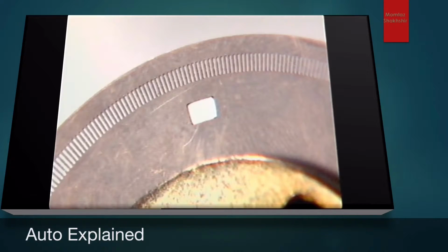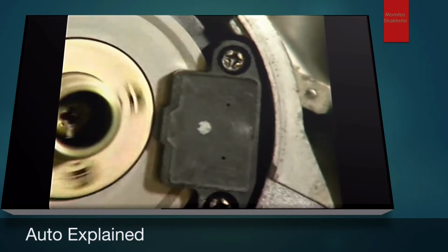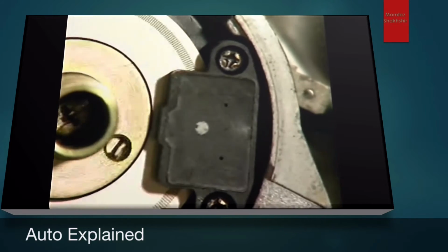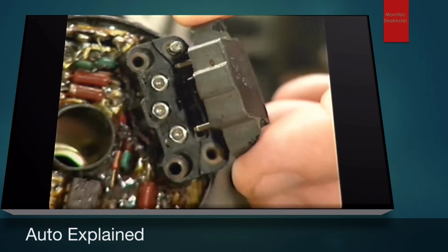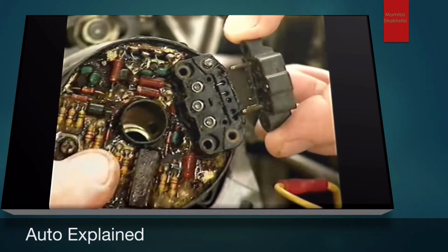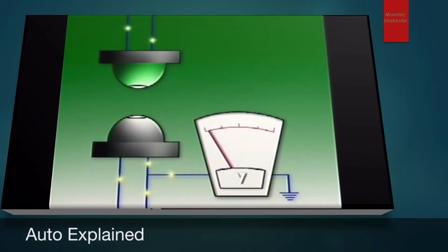As the rotor plate turns, it passes between 2 sets of diodes positioned in line with the slits. The diodes above the rotor plate are light-emitting diodes, while the ones below are photosensitive diodes. When provided with a suitable voltage, light-emitting diodes transmit a fine beam of light. Photodiodes receive this light and use it to make a voltage output signal.